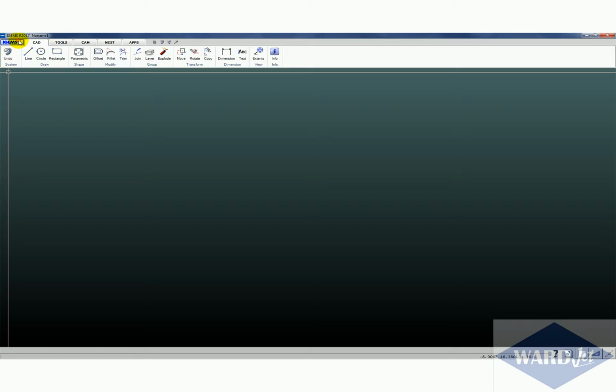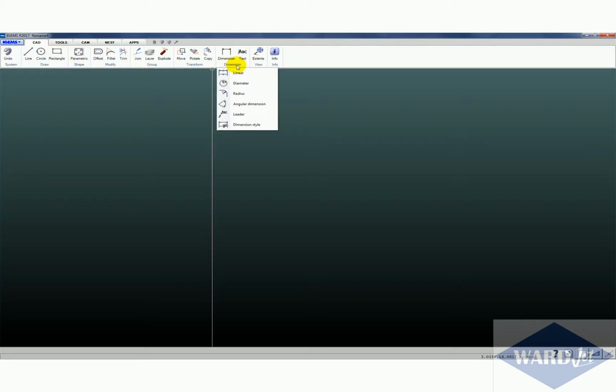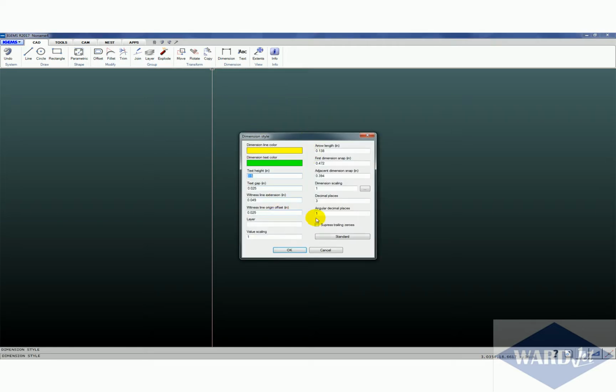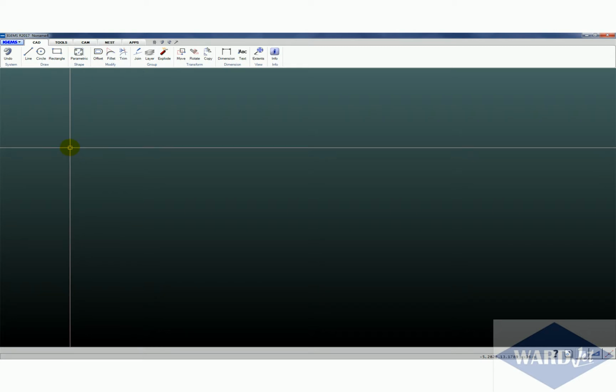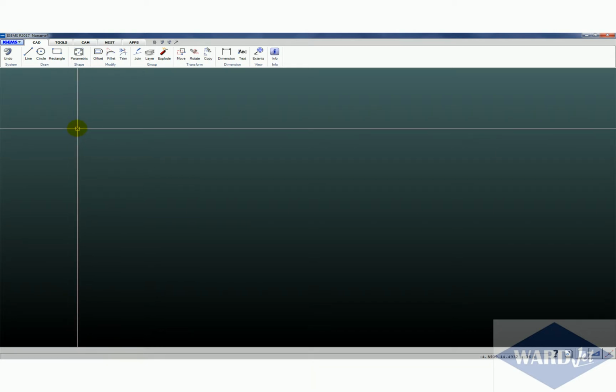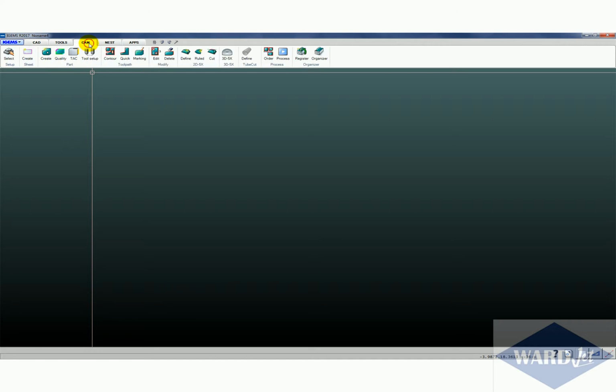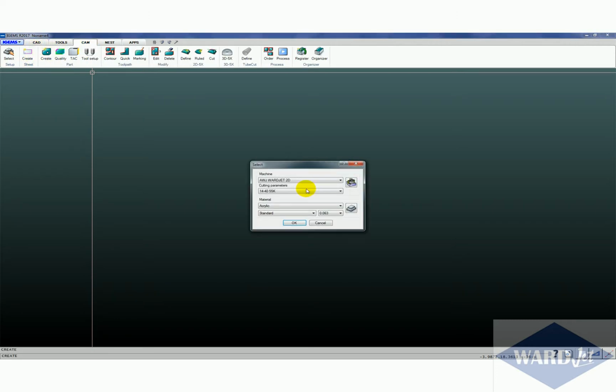So now, if I go ahead and do a new drawing, if we go to our dimension area, now we'll see that we've got our default dimension decimal places as 3, and our text height is 0.5, etc. So that's one area that that can be helpful. Another area that templates can be helpful is if you always use a particular sheet size, and you always want to have a sheet of that size in your drawing when you open it up. You can do that.